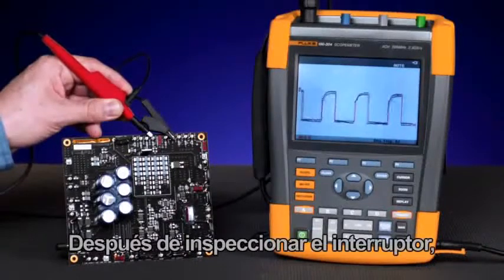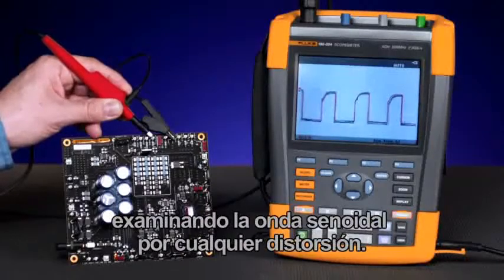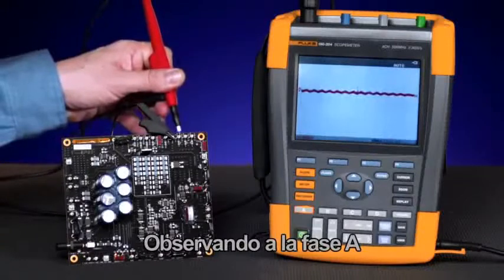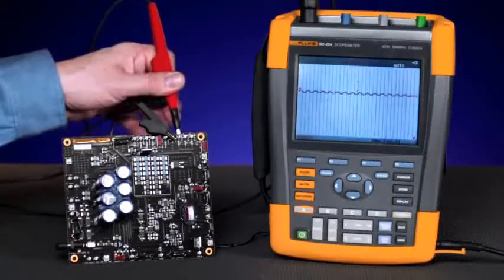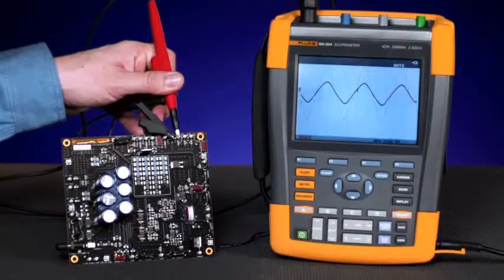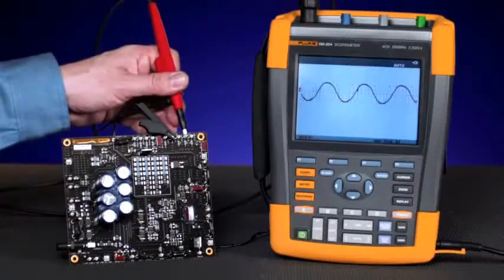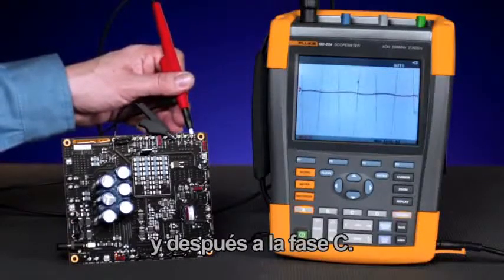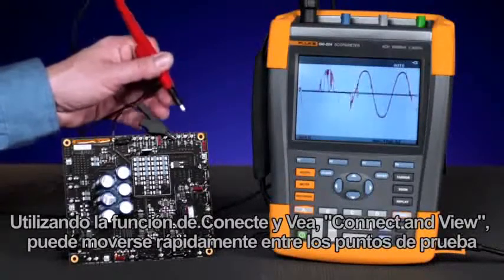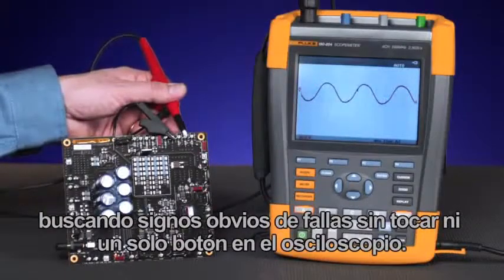After inspecting the switch, we can move to the three-phase output signals, looking at the sine wave for any distortion. Looking at phase A, to phase B, and then to phase C. By using Connect and View, you can quickly move from test point to test point, looking for obvious signs of failure without touching a single button on the oscilloscope.